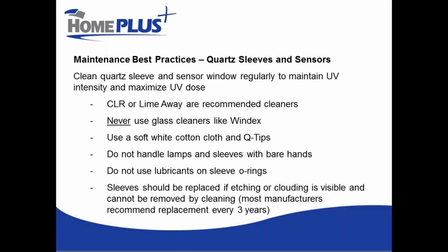And don't use any lubricants on the sleeve O-rings. It can be very tempting because it would certainly make everything assemble easier when you put things back together, but that lubricant will get on the sleeve, I guarantee it, and will, again, because it contains organics, absorb UV light and cause you a lot more harm than good.